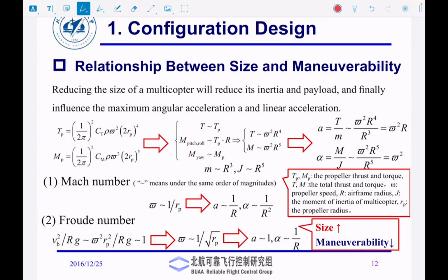Same thing happens in dimensional analysis. You have these seemingly unrelated quantities, but you combine them together, get some dimensionless numbers, and if the Reynolds number for this flow and the Reynolds number for this flow is the same, it means whatever measurements I make here, the same measurements would be replicated here. If I take another number, say Froude's number, and Froude's number for this airframe or this toy is the same as the Froude's number for this Boeing 747, whatever result I get over here can be used for the Boeing 747. That is basically the purpose of dimensional analysis.